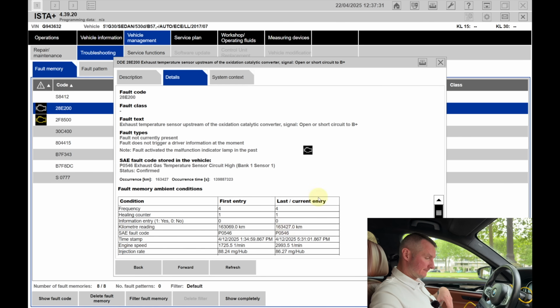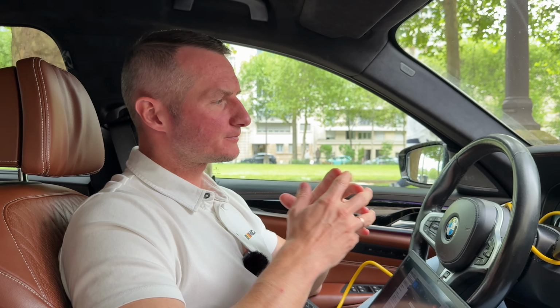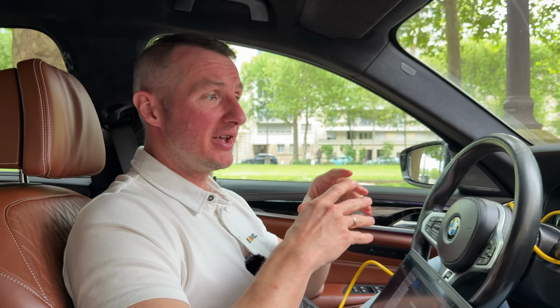What could it mean? Making the diagnostics is not only reading out the car with the help of the computer, you also have to understand how it works. Let's take, for example, the previous error we have seen. The error was present 4 times for 400 kilometers traveled. What could it mean? For example, if you have traveled 20,000 kilometers and the error appeared only once or twice, and the error is not active, you can just delete it and forget about it.